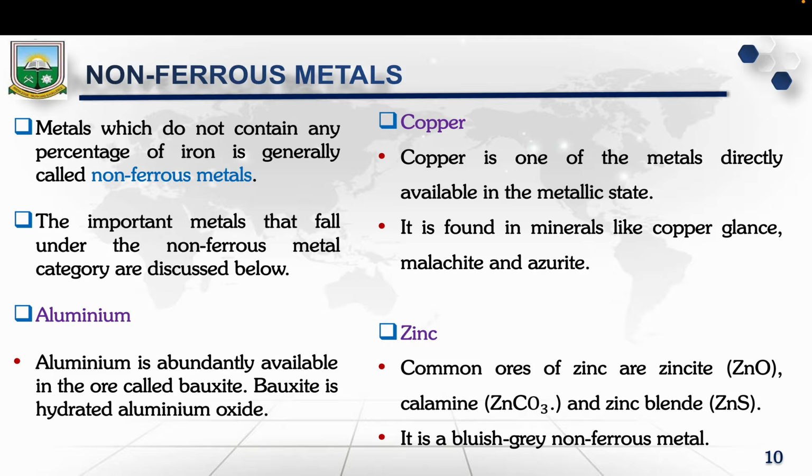Now, it actually makes zinc an essential player in extending the life of metal structures, okay, especially those in harsh environmental conditions, because during galvanization, the zinc is melted and applied like a paint, a finish to a metal, and it mainly prevents it from rusting, and it adds an extra layer of strength to the metal structure, okay. So in harsh environments where the environment is conducive for rusting, it doesn't easily rust, okay.